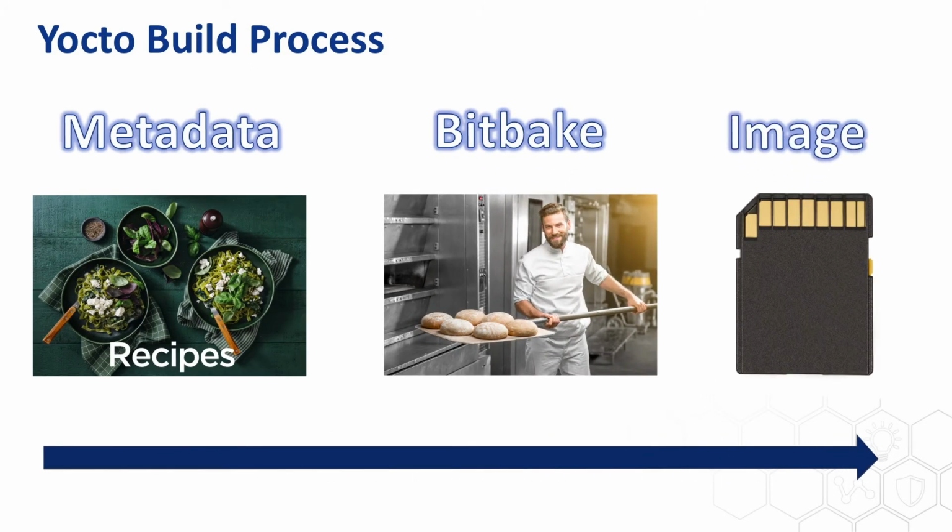The build is controlled by an executable called BitBake, which is responsible for processing the dependencies and scheduling the tasks using as input the recipes provided in metadata layers. Tasks typically involve fetching sources, configuration, cross-compilation, and installation on the target file system. Tasks are executed as far as possible in parallel based on the number of processors available.